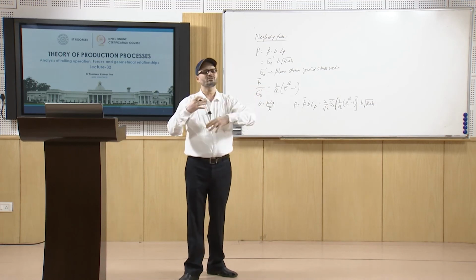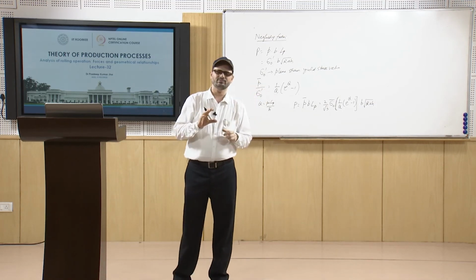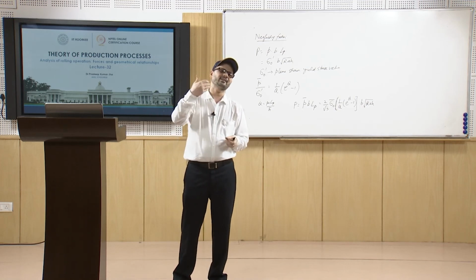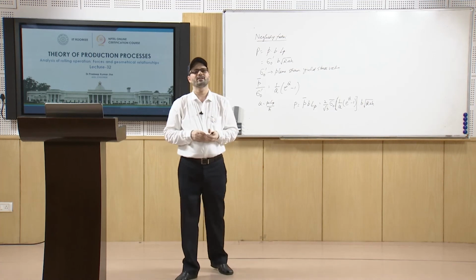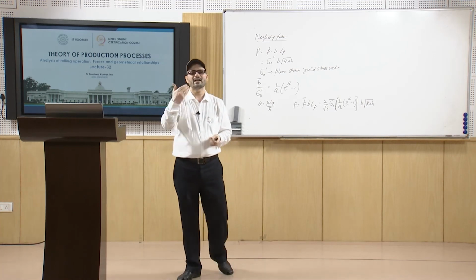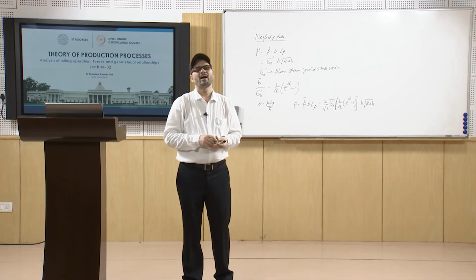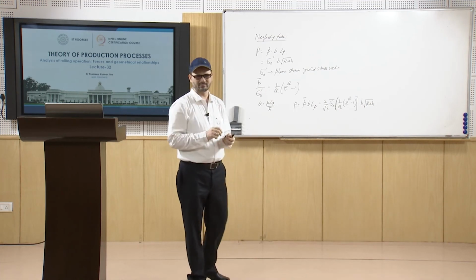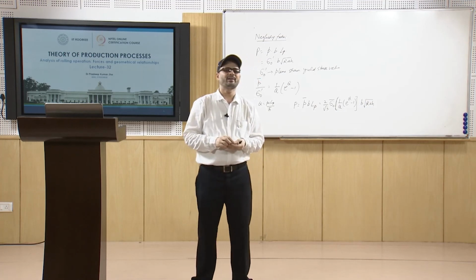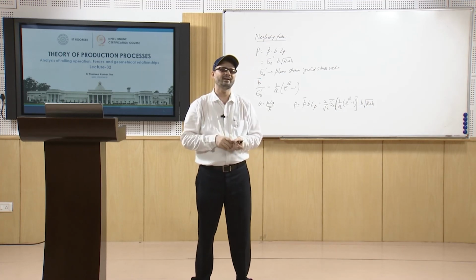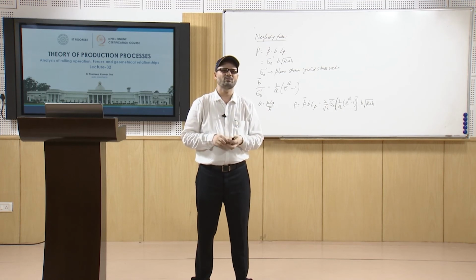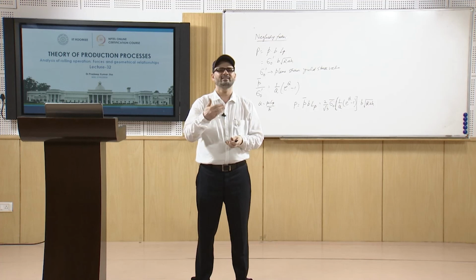You can also study the effect of hot working. In case of hot working, you have to study the effect of strain rate, so the strain rate term comes into the picture. In case of cold rolling, we have seen the maximum reduction possible depending upon mu and R. So, this way you can calculate the rolling load and other possible reductions. Thank you very much.